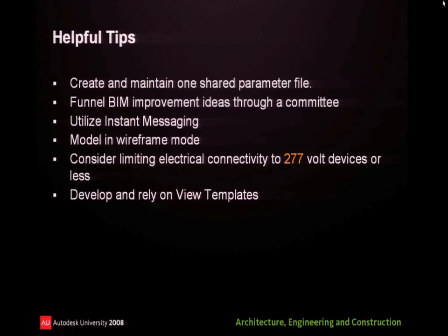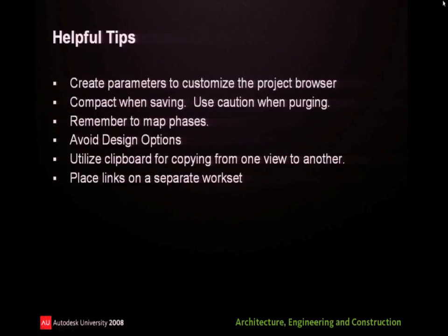And view templates, those are very powerful as well. Rely on those. Customize your project browser. Compact when saving, but be careful about purging. We have found, as a lesson learned, that if you purge out all your unused families or types, you come back, you want something back, it's hard to get back the family you purged. It's difficult to get it back in there.